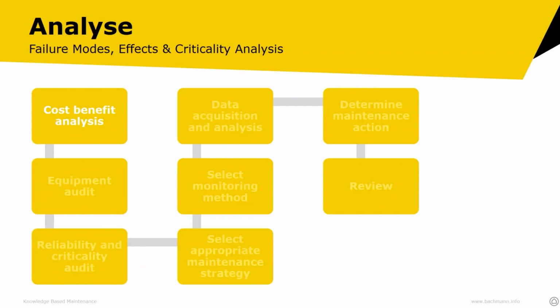So what we actually do is we follow one of the ISO standards through, which has a lovely little process to take you through what's called a failure modes, effects and criticality analysis, known as FMECA for short. It basically tells you how to do a cost-benefit analysis across your whole plant to decide which bits need which sort of maintenance. It's a standard that's come from the condition monitoring area, but it doesn't just say you've always got to do condition monitoring. It's much more generic than that.